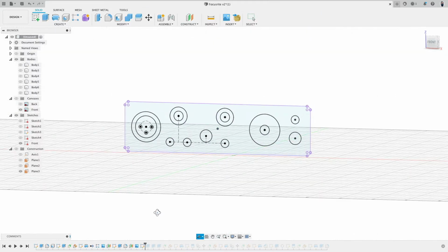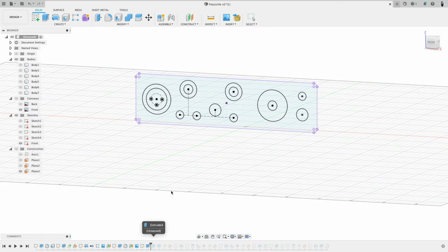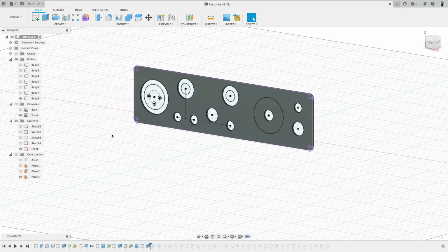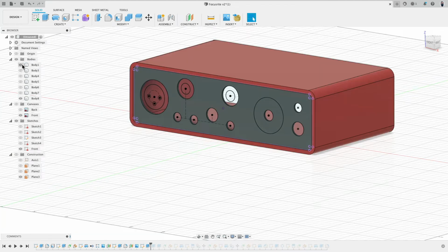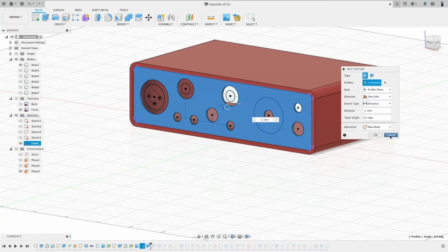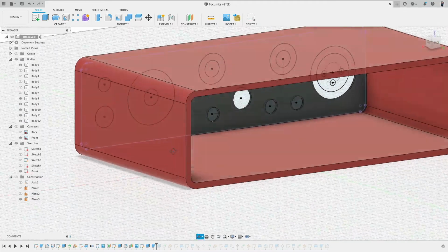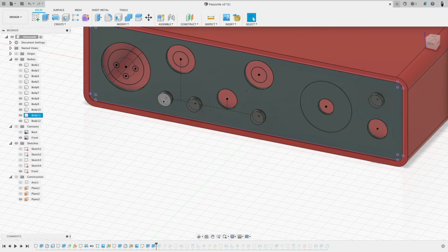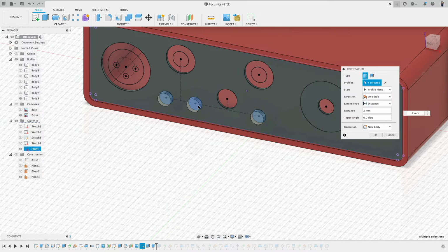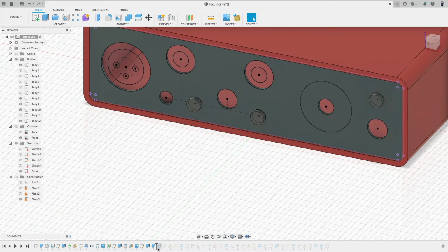With this sketch done, the next step is simply, well, we extrude this front plate out. Also here, this front plate extrudes into the body as a new body. Okay. What do I have here? I have 2 dials. So dials and all these things are obviously pre-made components. And since we would like to create a rendering, I simply made myself some dummy pieces. These are just extrusions from the sketch profiles from these 3 rings. Also new body. Very good.